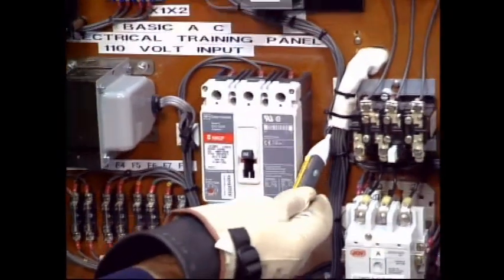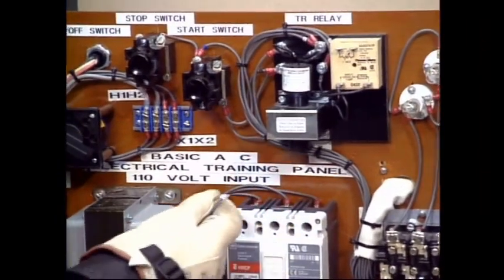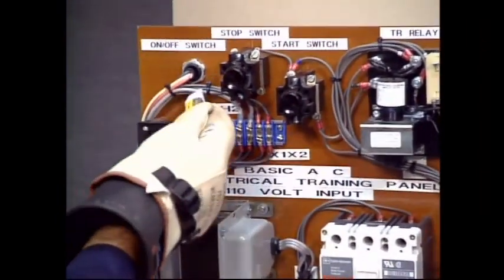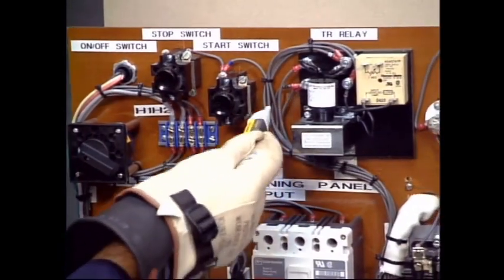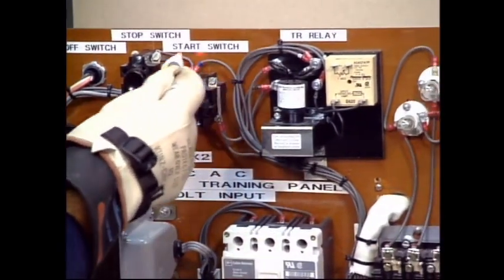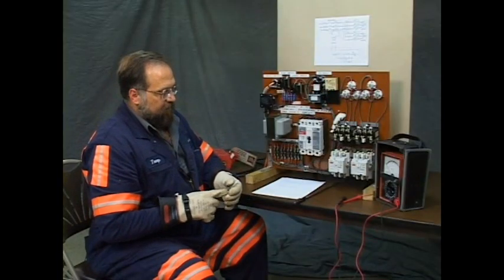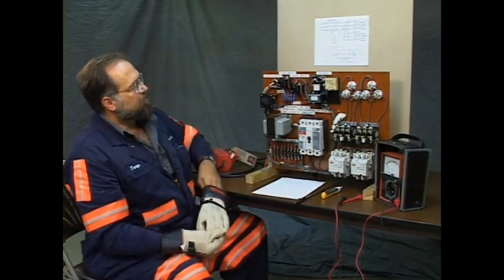That's not indicating there's power here. It's indicating the voltage tester is turned on and it's operating. We don't have any power on. It would be locked on and staying with an audible alarm and an uninterrupted light. I believe we're safe to take the gloves off and make some continuity tests.